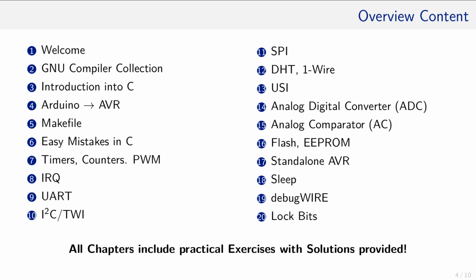And from then onwards, we concentrate on the periphery that the AVR architecture offers. As an example, the ATmega328P is taken, but there are many similarities among the AVR MCUs. We will start with timers, and we will not only see how to configure those, but also how they work internally. The same is true for the essential interrupts and all the communication protocols which the AVR supports or even does not, and what to do about that.